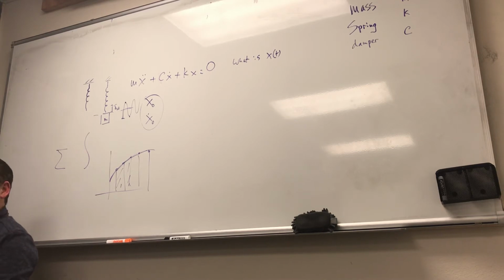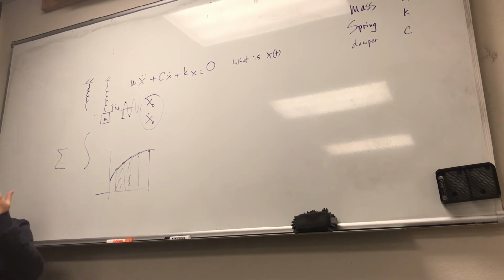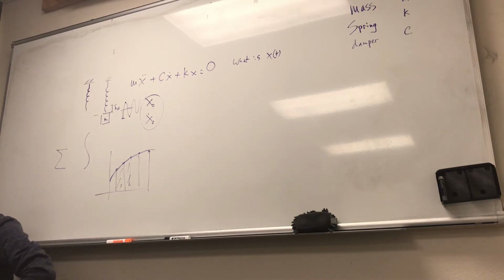Forced vibration, now we can tell it's the opposite of free vibration. If a system is now subject to an external force, that means the mass, if I take the mass and either maybe by hand try to force it at a certain frequency, in other words, give it an amplitude and frequency, then the big question is, how is this mass going to respond? So if a system is subjected to an external force, often a repeating type of force, the resulting vibration is now called a forced vibration.